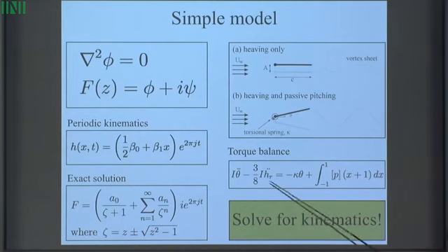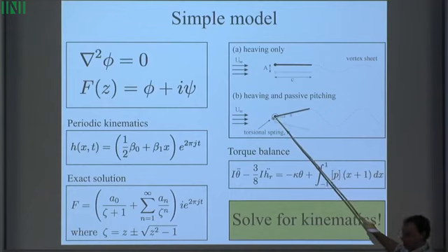On the left, I have angular acceleration terms, and on the right, I have all the torques acting on the wing. So this is the torque due to the spring. You see that spring constant there, and the angular deflection. And then this represents all the fluid forces. So this box P, that's the pressure jump between the top and the bottom of the wing. And I integrate that against distance, and that gives me the total torque induced by the fluid on the wing. So your wing is not flexible. All the flexibility is located at the torsional spring.